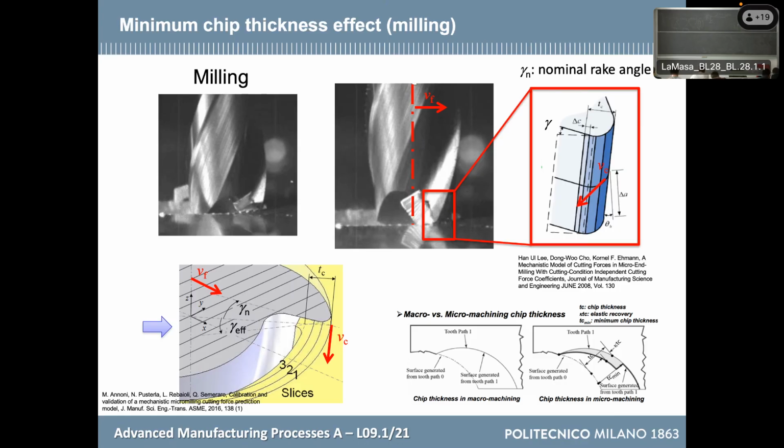But be careful, because you could imagine that you could solve this issue if you select an Fz that is big enough. In reality, it is not like that, because even if Fz is big, for sure you overcome the minimum chip thickness at the center, where the chip thickness is high. And if you increase Fz, the two tracks are creating a bigger chip thickness. But in any case, at the entrance, at the exit, the chip thickness will always tend to 0.